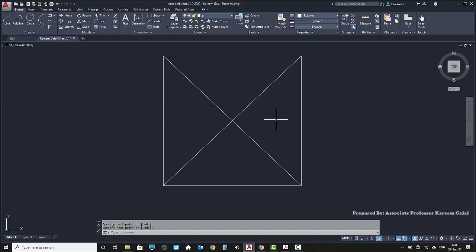Now we are going to draw the two perpendicular lines from the middle of the square sides. Activate the line command again. Move to the midpoint of the upper side. Click to select it. Move down, select the midpoint of the lower one and deactivate the command. Repeat this action for the horizontal one.